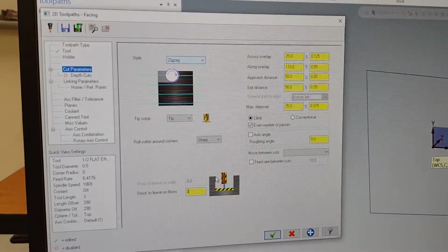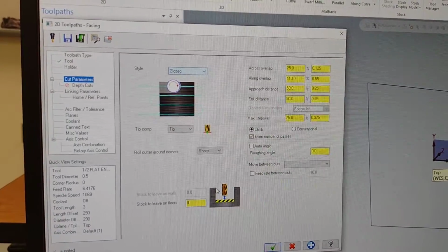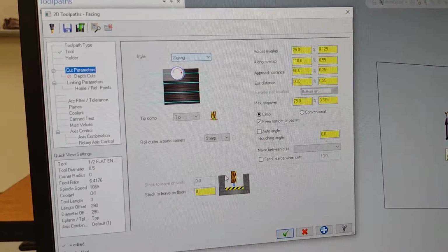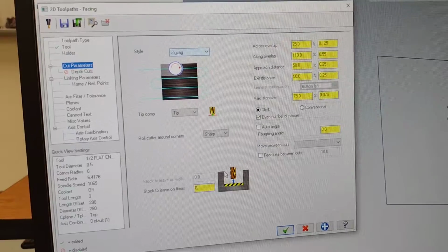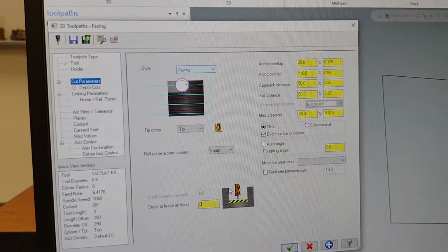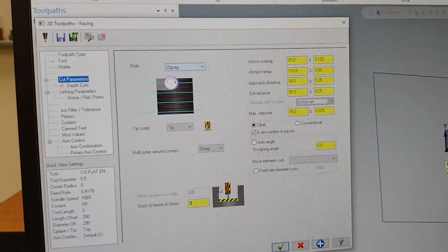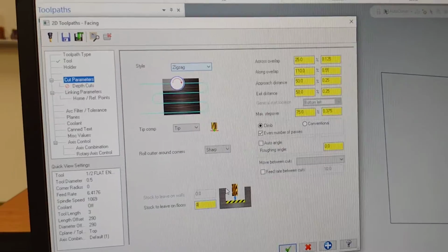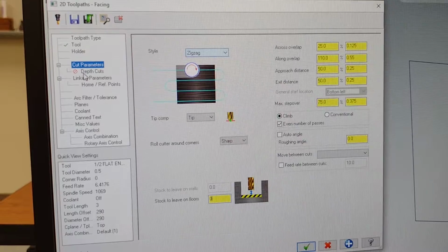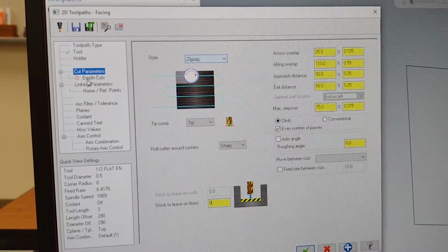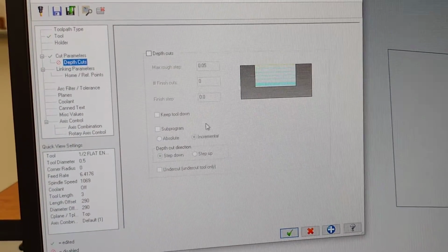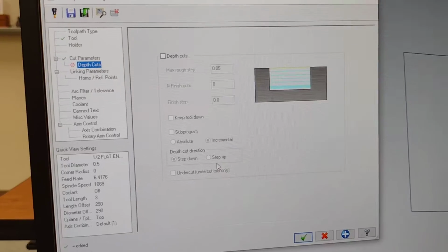You don't typically on official parts, that's the process. You're going to do some rough and finish. You're not going to come in and clean up one side to finish and then go rough and finish as you go. You're going to kind of whittle it down all together as much as possible. And then, you know, if we had a lot of material to take off, we could turn this section on, and this would give us depth of cuts. We leave it off for now.